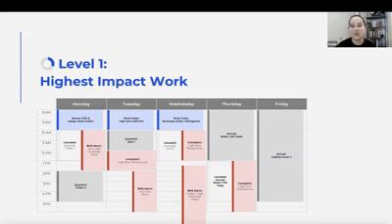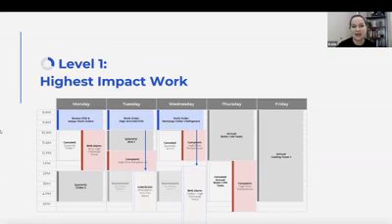You're saying Tuesday and Wednesday, I'm going to hit these 2 items and I'm going to get those done this week. And by doing that, when you hit that AHU that had a high kW per CFM that was maybe telling you your fan was probably not operating optimally, you upended that BAS alarm for your fan failure.